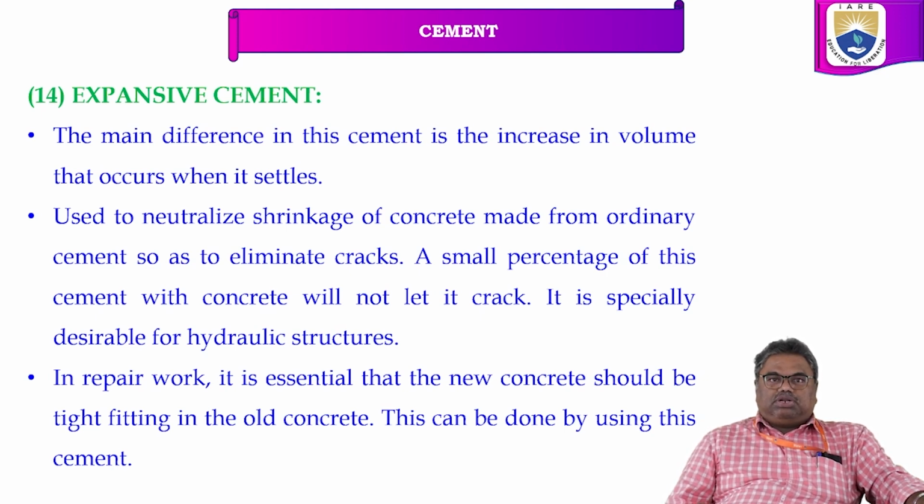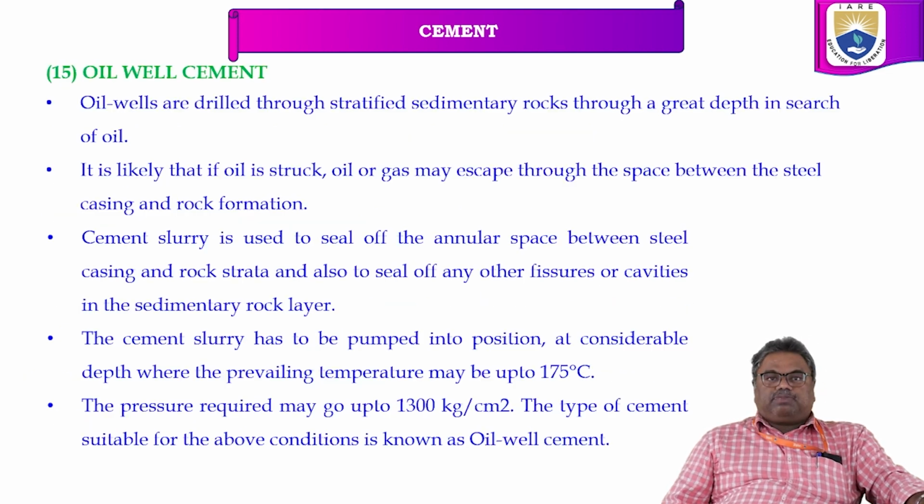It is especially desirable for hydraulic structures. Hydraulic structures are very important structures, and you should not have cracks in them. If you use this type of cement, you can reduce cracks and get a kind of self-repairing concrete. In repair works, it is essential that the new concrete fits tightly in the old concrete, and this can be done by using this cement. So for the repair of any structure, you can use expansive cement.